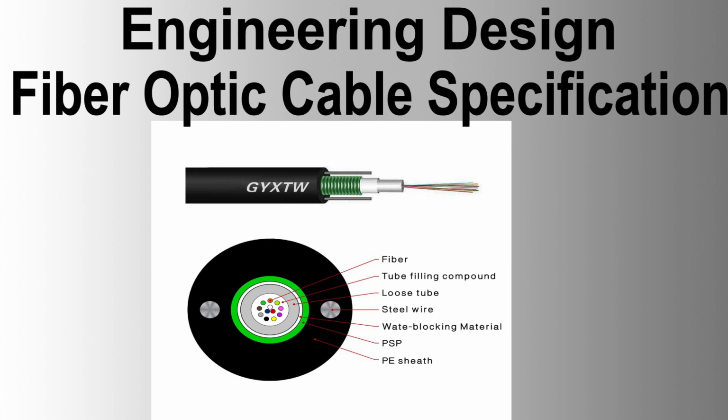Acceptance tests. Final inspection. The acceptance tests shall include optical time domain reflectometry (OTDR) measurement, testing length and attenuation for each testing length. For runs over 100 meters, the test shall be made at both ends and the two measurements compared. Differences greater than the instrument resolution shall be investigated and resolved. Attenuation measurement. Ensure compliance with the design specification. Graphic summary, backscattering diagram, used for localized losses detection during installation.